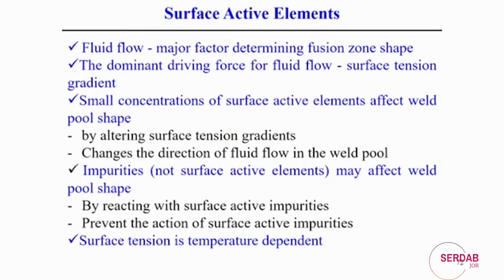of the cases we normally neglect this fluid flow effect, and we always try to do the heat transfer analysis using only the heat conduction within the weld pool. That means we generally assume a stationary molten weld pool, but if you look in depth at the analysis of the weld pool, the molten metal actually flows in a specified direction, and that flow is driven by different driving forces, mainly the surface tension force, which is mainly responsible for the liquid metal flow within the weld pool, and of course indirectly that flow also affects the shape and size of the weld pool.